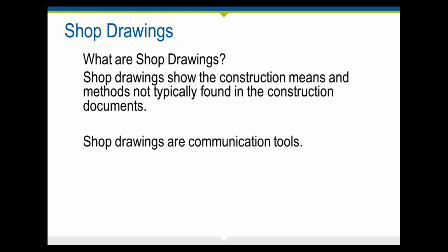You, in that case, if it is indeed a delegated design responsibility, you are responsible for specifying all of the performance or design criteria that must be satisfied. And you're still responsible for reviewing and approving the contractor's submittal for conformance with the design concept. Just because they have engaged or are required to engage a licensed design professional does not mean that you are not still responsible for reviewing the submittal to make sure that it conforms with the design concept that you have shown in the drawing.